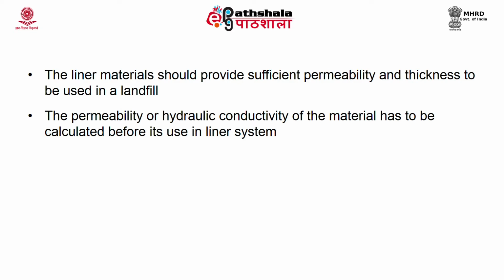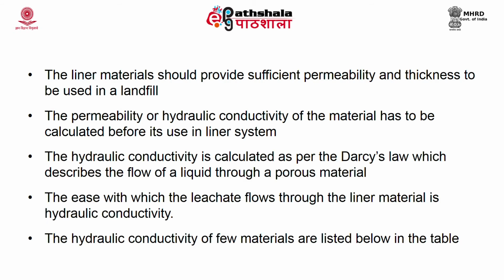The permeability or hydraulic conductivity of a material has to be determined before it is used in a liner system. The hydraulic conductivity is calculated as per Darcy's law, which describes the flow of a liquid through a porous material. The ease with which the leachate flows through the liner material is called hydraulic conductivity. The hydraulic conductivity of a few materials is listed below in the table.